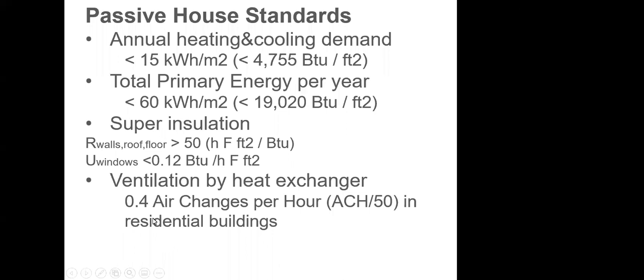Basically, with commercial buildings, we cannot set a limit in terms of air changes per hour because it depends on the number of people. We can have commercial buildings with thousands of people and commercial buildings with 20 or 50 people. But in single family houses, we don't have thousands of people living together. At least it's not convenient.